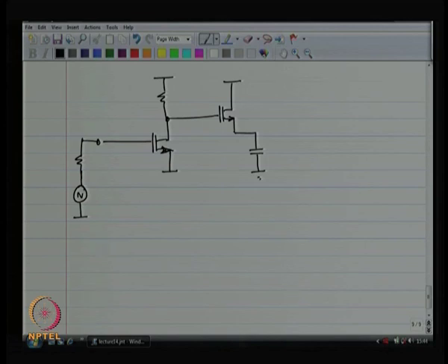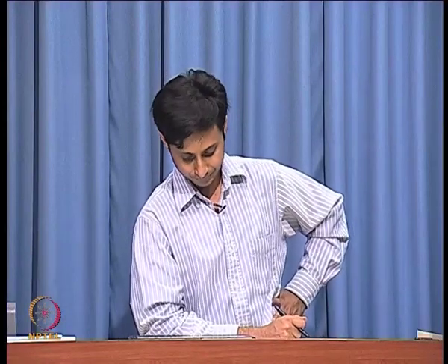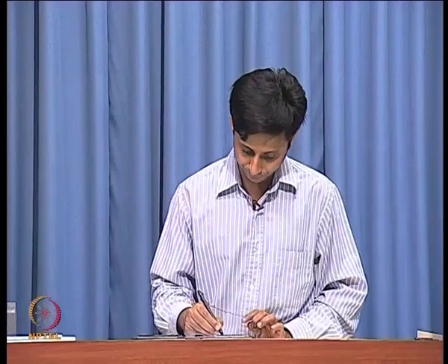Let us say that I split the load into the resistive and the capacitive component, just for doing it, okay. And let us say I place the 2 kilo ohms over here, that was my load resistance, and the 1 picofarad over here. So, I am basically buffering, I am putting a source follower to drive the 1 picofarad load capacitance, okay. So, this is my new plan, new game plan. And I now have to work out what is the bandwidth of my new circuit. So, to work out the bandwidth of the new circuit, we need to place all the different capacitors.